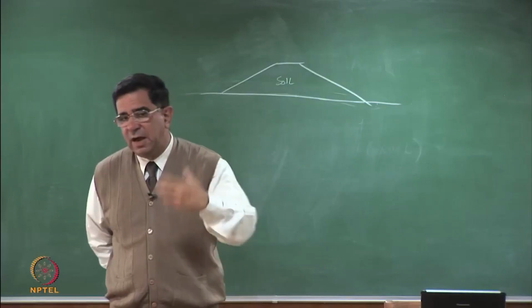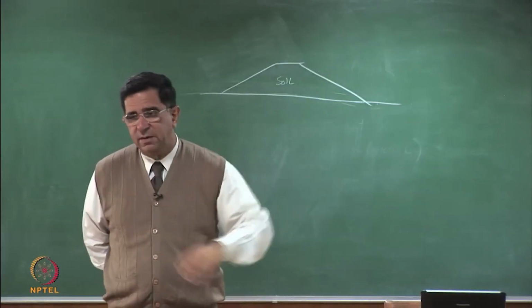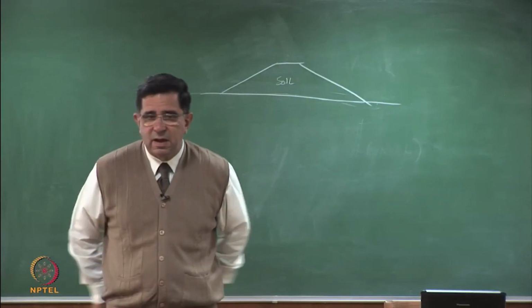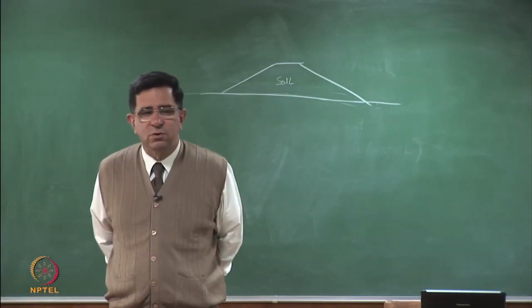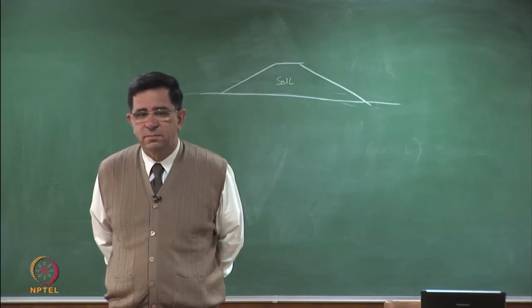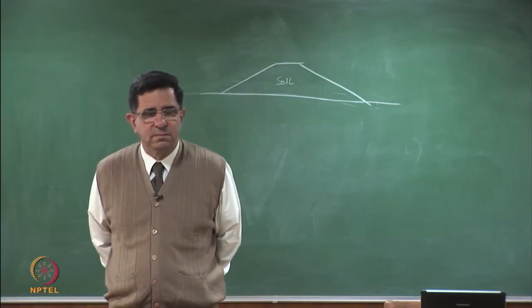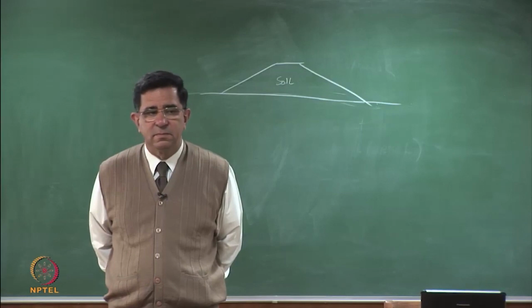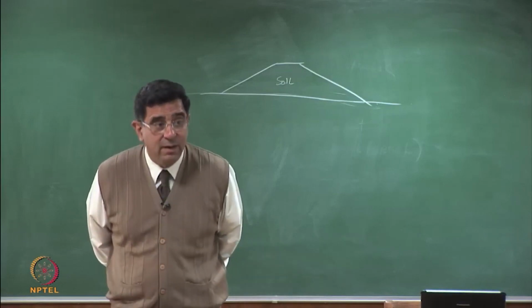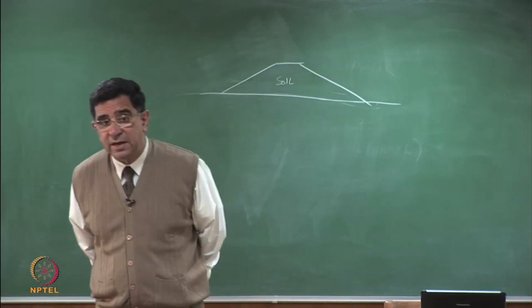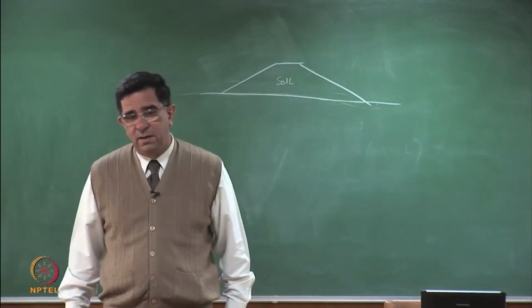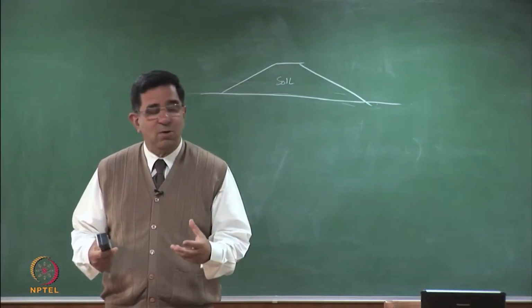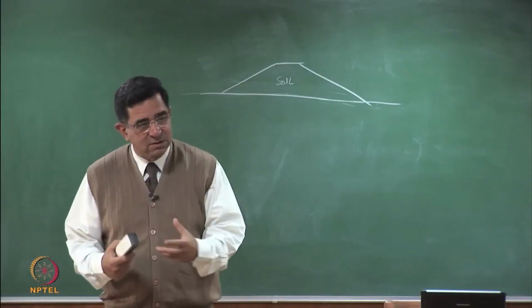But let's first forget about heterogeneity. I give you some waste. I ask you to find out its shear strength parameters. What test would you do? Pardon? Large box direct shear is a good starting point, because I don't know how the sample consistency will be.